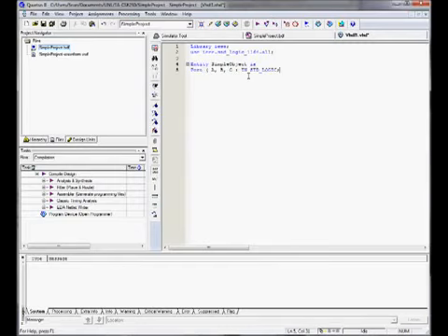We're going to make one more. We're going to have a result, and it's going to be an output. And again, standard logic, because it helps to have things that match up. You can do it without matching them up, but it gets a little bit messy. One note there, I just deleted the semicolon at the end of standard logic. VHDL needs that in order to do the port. It actually has it right here. So that's one kind of weird programming construct that you need to wrap your head around. Finally, now that we've defined what our simple object is going to be, we're going to end it. So we're going to end simple object.